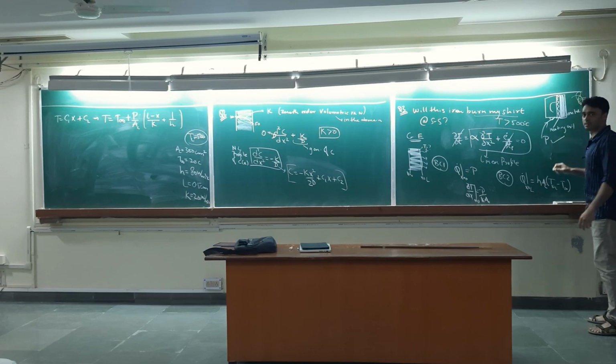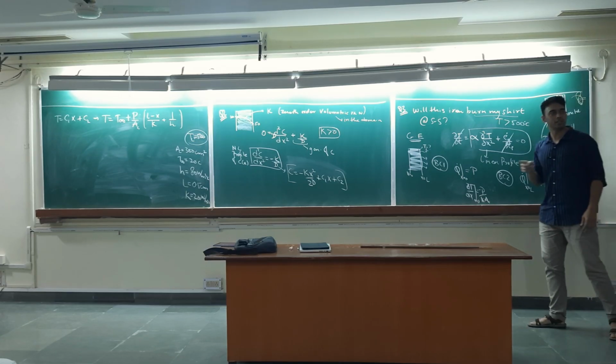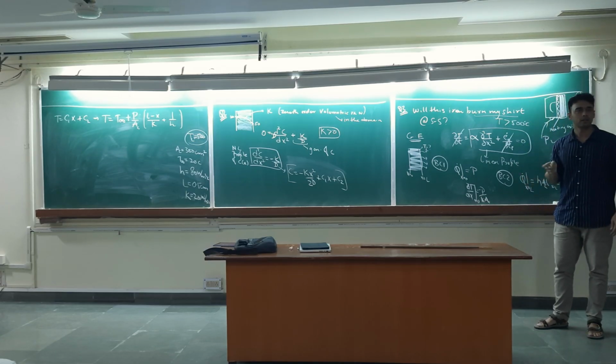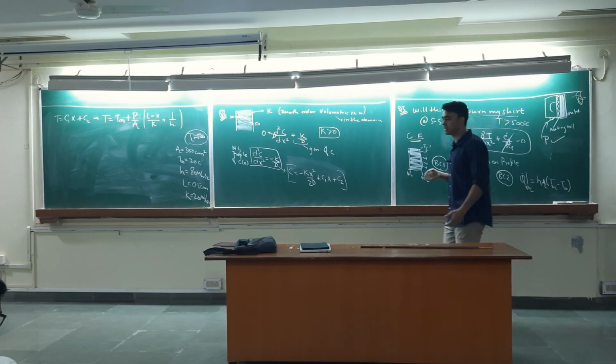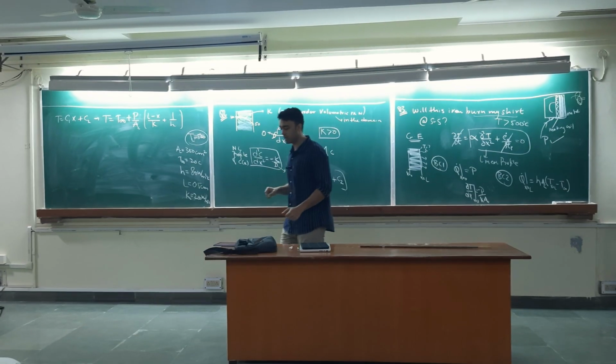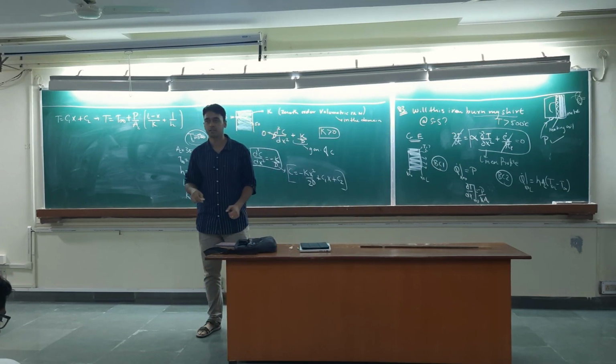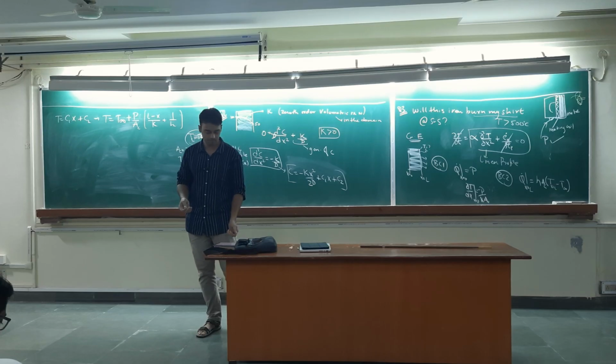By turning on a fan. So you increase the fan speed, your heat transfer coefficient will increase, right? That's the reason when you go on a bike in winter mornings, you tell your friend, "Hey, go slower, I'm feeling cold." Why? The temperature is the same. The heat transfer coefficient is different, right?